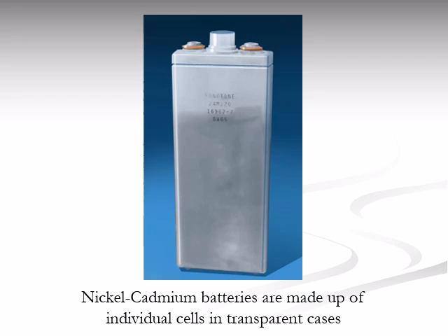However, they require careful maintenance, especially with regard to cell balancing, venting, and electrolyte management, to prevent issues like thermal runaway or cell reversal. Regular servicing and proper charging techniques are essential to keeping these high-performance batteries operating safely and reliably.